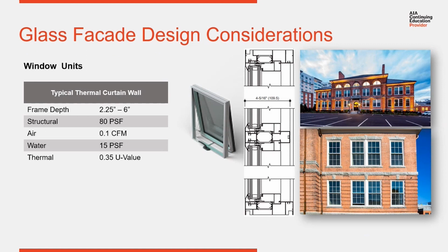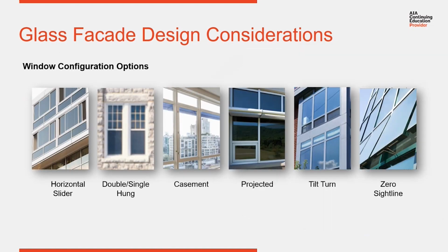I mentioned earlier that commercial Windows kind of started the drive in glass and glazing toward unitized construction, because the model with commercial Windows was to bring a pre-built, pre-glazed unit and fill a punched hole. So it was modular construction, and then we had a rough opening, and then bang, a window goes in, it's closed up. That was the model started by commercial Windows, and that's still being used in all the various